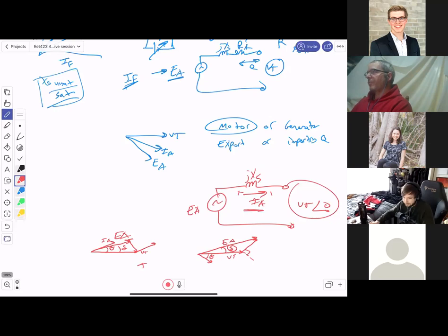Way at the beginning of the semester, what did we say about current going out of the machine? What really dictates whether that is going in or out of a box? What really dictates the direction of I? Whether it's a motor or generator? Whether it's a load or a source, right? Source. Load, it's generic, right, to say anything. So the direction of P will follow, and the current direction follows that way. So since IA is in the out direction, that's P. So whether it's leading or lagging power factor, our delta was always positive.